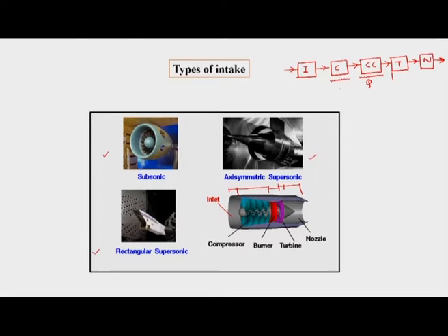While increasing the pressure in the compressor, we need to give W in, and we give Q in in the combustion chamber. By means of the intake, we want to reduce this W in, such that our work requirement would decrease.